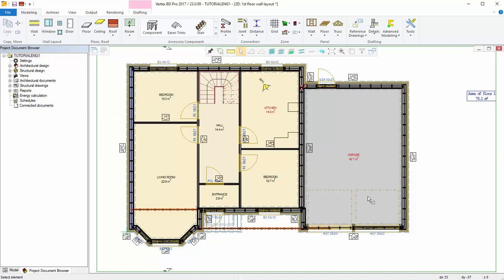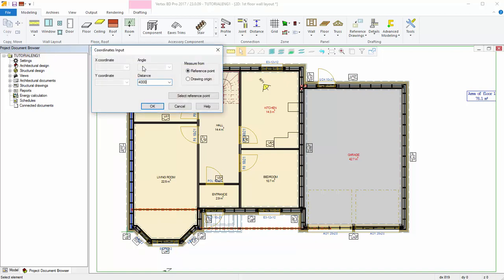You can reset the coordinates by setting a local origin. Place the cursor to the desired place and press Q from the keyboard, which makes a new local origin to that place. In this way, you can, for example, give a distance from a point.